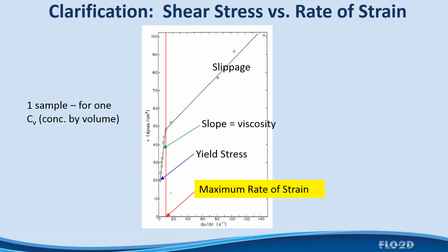And the other clarification that I wanted to make, it's not so much a clarification, but just a highlight. I talked 2 weeks ago about mud flow laboratory analysis and how to get them. And we had a question about the shear rate for this. And then I discussed with you the potential to use different types of commercial viscometers and so forth. One thing that I failed to mention, or that I might have mentioned, but let me highlight here, is that you need to run any commercial viscometer or any laboratory viscometer on the same order of magnitude that you would see in the field conditions.